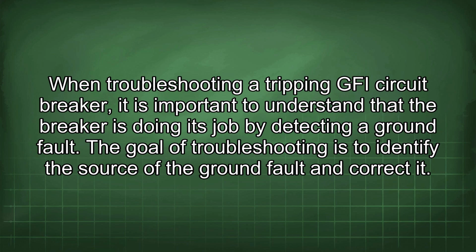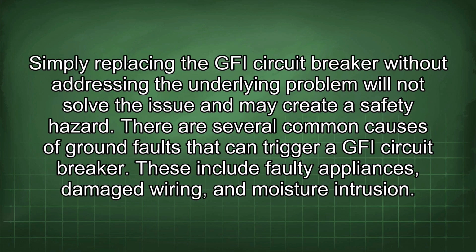When troubleshooting a tripping GFI circuit breaker, it is important to understand that the breaker is doing its job by detecting a ground fault. The goal of troubleshooting is to identify the source of the ground fault and correct it. Simply replacing the GFI circuit breaker without addressing the underlying problem will not solve the issue and may create a safety hazard. There are several common causes of ground faults that can trigger a GFI circuit breaker.